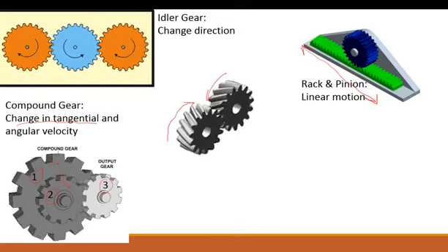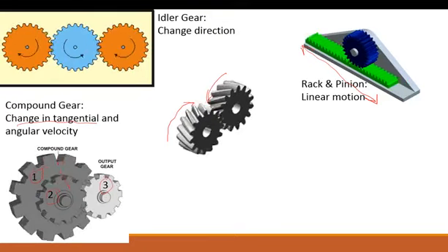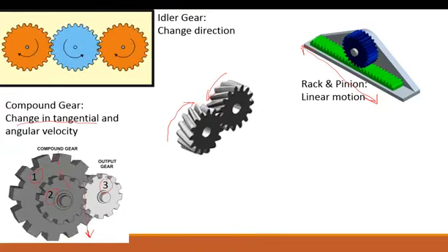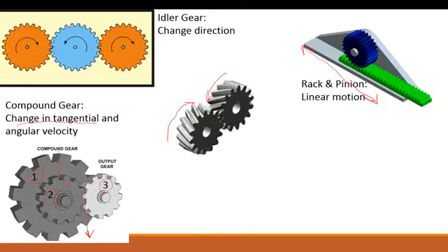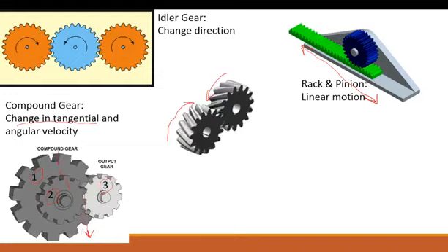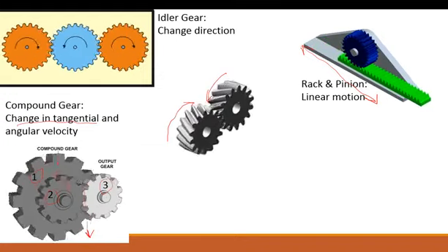Here you have these two gears, and we're not going to make any assumptions on their diameters, but regardless of that, they do have a common tangential velocity. Same as you would see with this rack and pinion. So that tangential velocity translates to the same tangential velocity here, and this is still along the pitch line. Both of these are along their own pitch line.